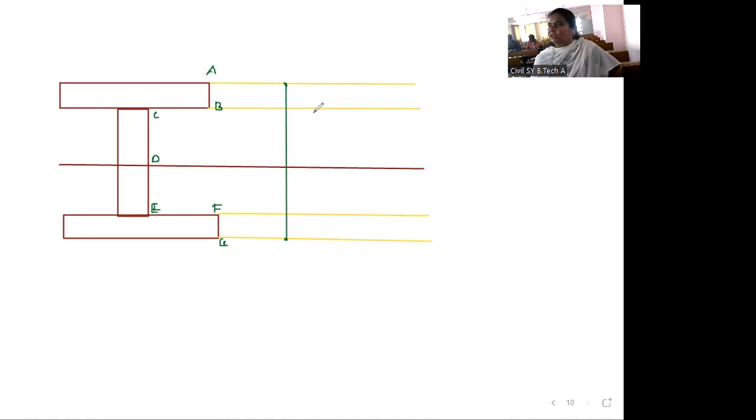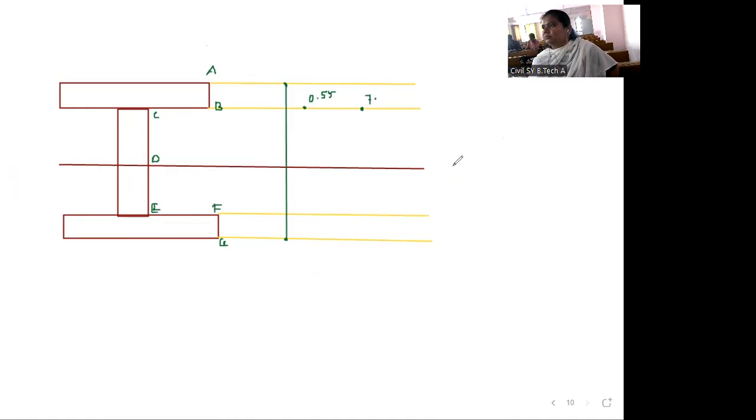After that shear stress at B. Shear stress at B is 0.55. After that shear stress at C. जे त्याच लाईनला पॉइंट आहे बघा तो. ठीक आहे. So shear stress at C is 7 point something ना. How much? 7.65. So 7.65. Okay. And shear stress at D, maximum value here 0.64 into 10 raised to 6. Now first we will mark E. So shear stress at E is same 7.65. At this point shear stress at F is similar to this 0.55.